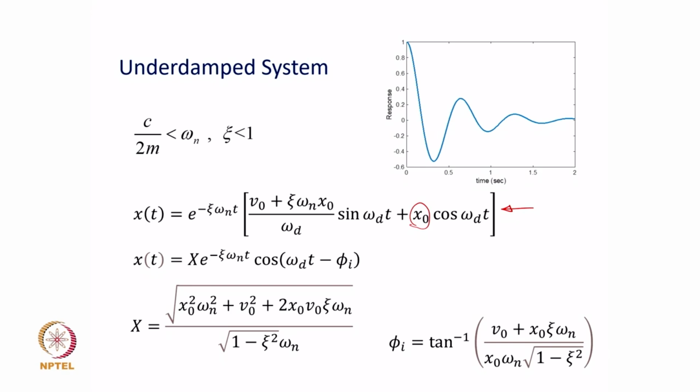So, given your vibratory system, which you will convert from a physical vibratory system by making a simplified model something like this, which has its own k, c and mass values, if this system is perturbed at t is equal to 0, the ensuing vibration response can be obtained by the expressions which are given here.